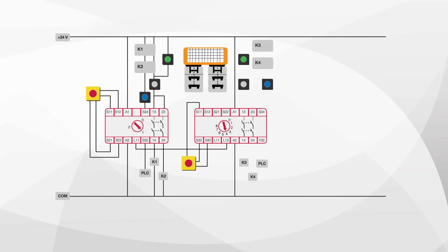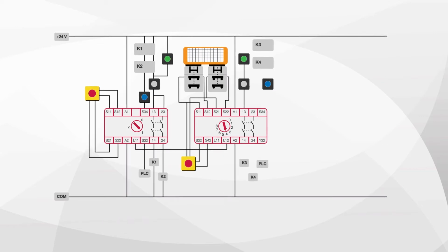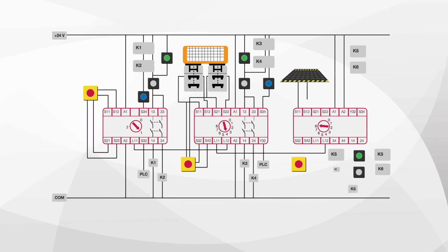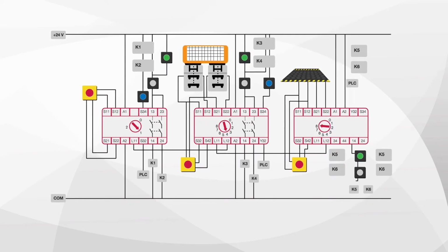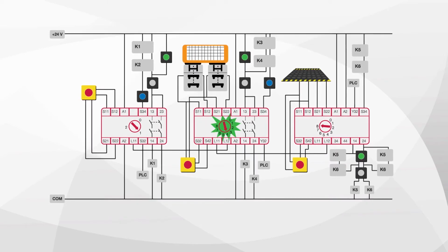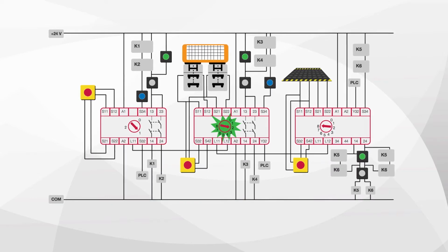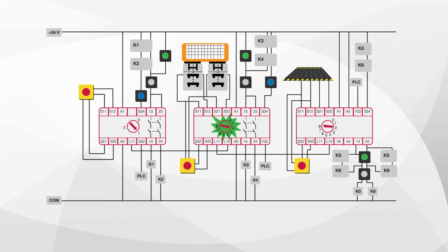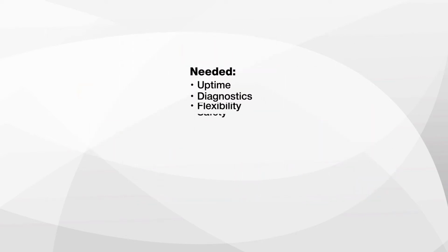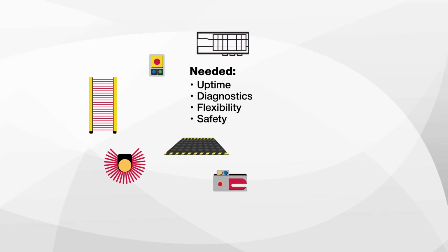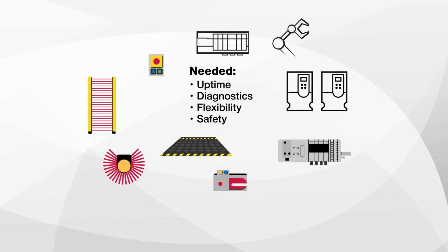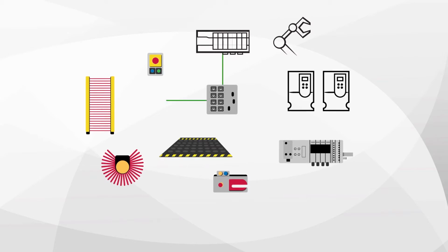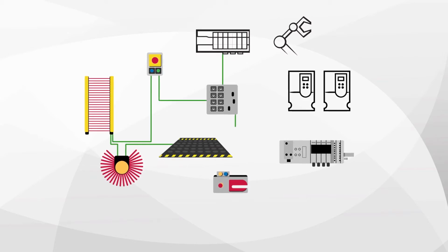As the system grows to include more inputs and outputs, though, wiring becomes expensive and difficult to troubleshoot, while diagnostics are very limited. If new functionality is needed, these systems require significant rewiring and new validation efforts. If you are using hardwired safety circuits and relays, contemporary safety systems with more intelligence, connectivity, and extensibility could boost your bottom line while keeping your facility safe.